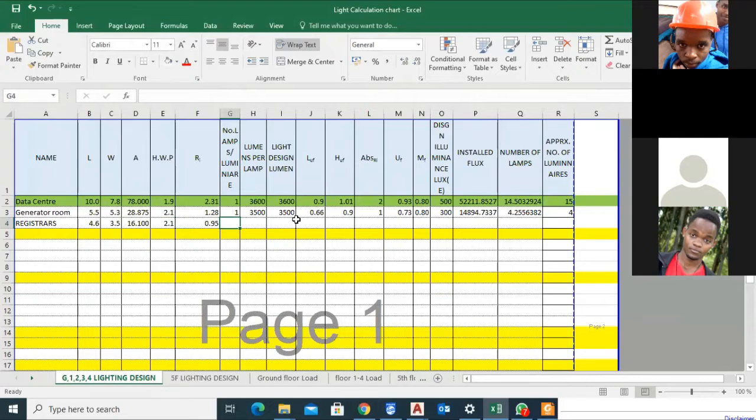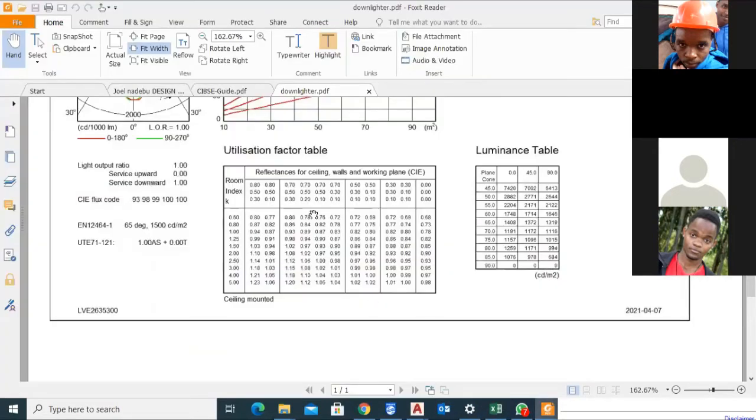We are using 0.86, and then adding the difference between 0.93 and 0.86 over 1 minus 0.8, multiplied by the room index minus the lower one. For the range 0 to 1, I go with whole numbers.